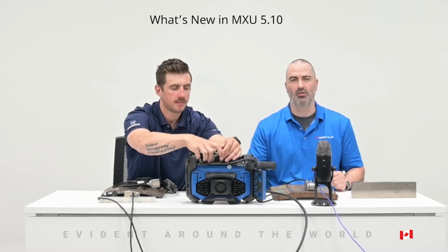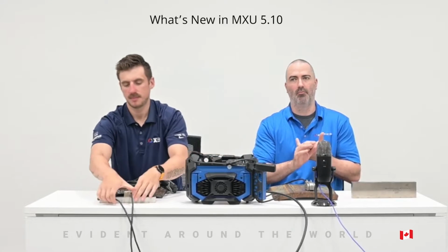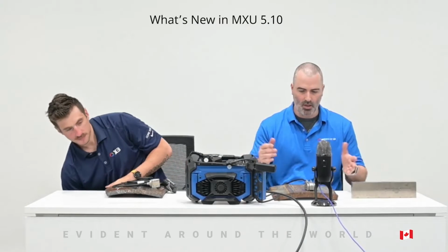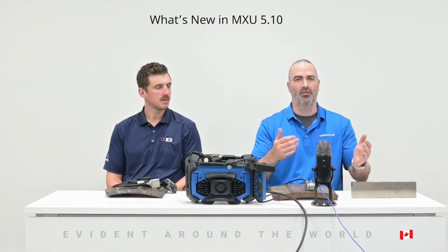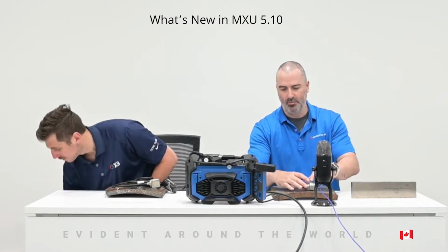We now support TFM with the dual linear array and dual matrix array probes that we offer, for both angle beam and 0 degree. Moving on to this part, we have a sample that has some H2S blisters with connecting stepwise cracking, and we're already pre-set up.